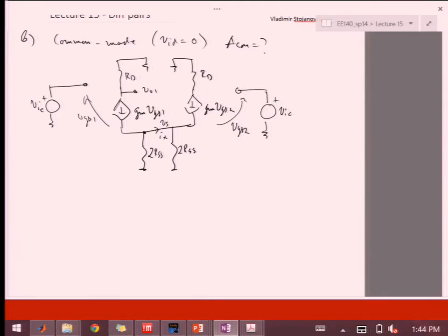It's also going up, right? Is this voltage any different than this voltage? No. So the currents are the same, resistors are the same, everything is the same. Essentially, because of that symmetry, Ix equals 0. There's no imbalance in this circuit that would cause more current to flow through the right half than through the left half, simply because everything is driven the same way and everything is identical.